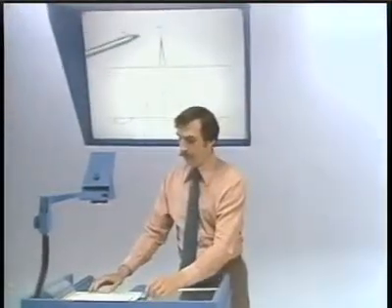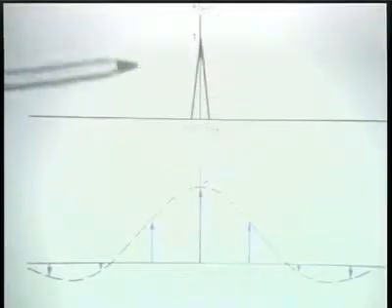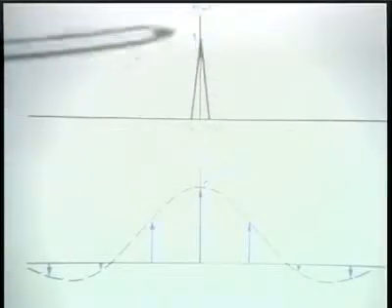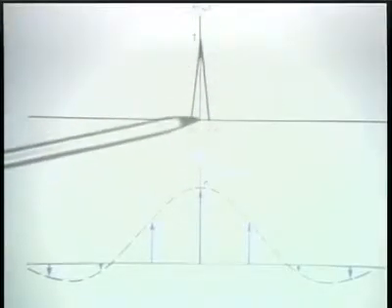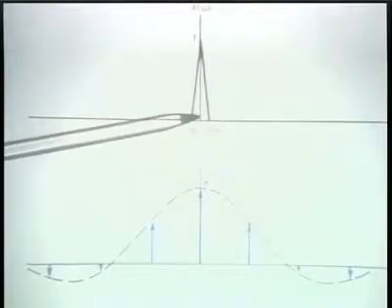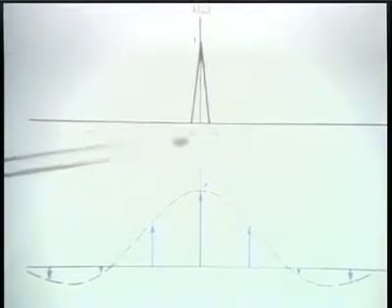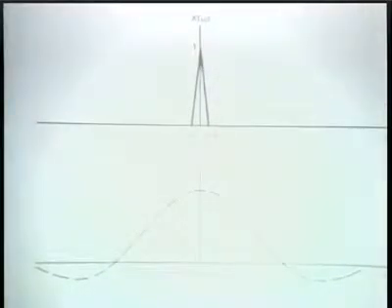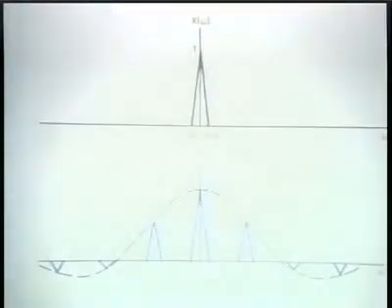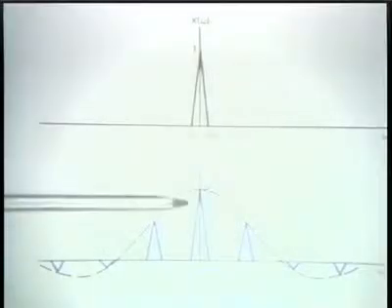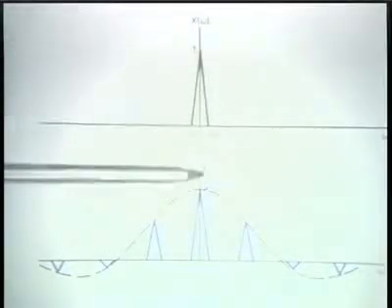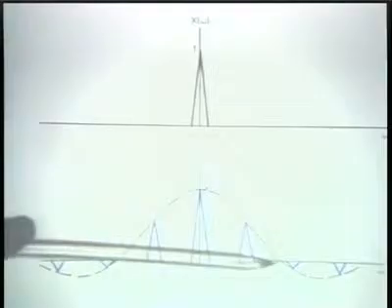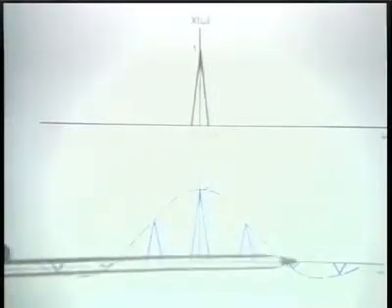If we were to consider, let's say, a Fourier transform, which I have chosen as more or less a general one, then when we convolve this with this impulse train, what we end up with is a replication of this spectrum at the places in the frequency domain where the individual impulses occurred.